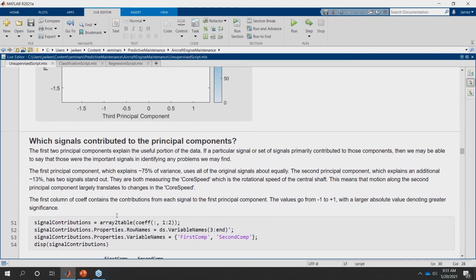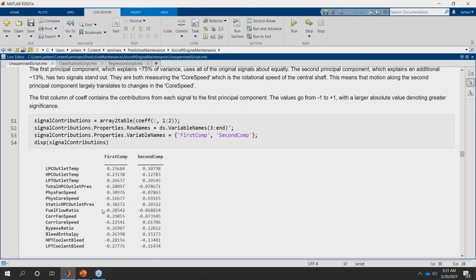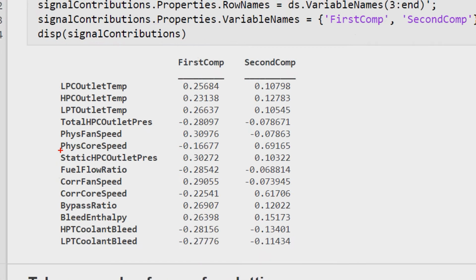All right, so when we move to these principal components, we do lose the sense that they correspond to a specific physical value. You can't say, oh, principal component 1 is the temperature. It is a combination of all of our sensors, a weighted combination of all of our sensors. And we can look and see what that combination is right here. You can pull that right out of the principal components. It's not hidden or a secret or anything like that.